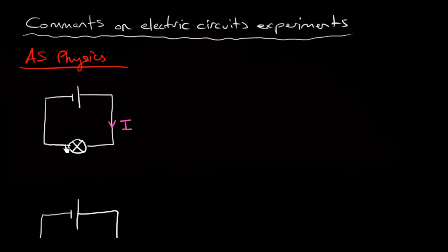And you can talk about two things happening in this circuit very simply. One of them, you can put an ammeter here in series, and you can check that if you put it on this branch of the circuit or in this branch of the circuit, the current is the same, because it's just going around the loop, and Kirchhoff's law says that no current is lost. So that would happen if you would connect an ammeter to those 2 points.